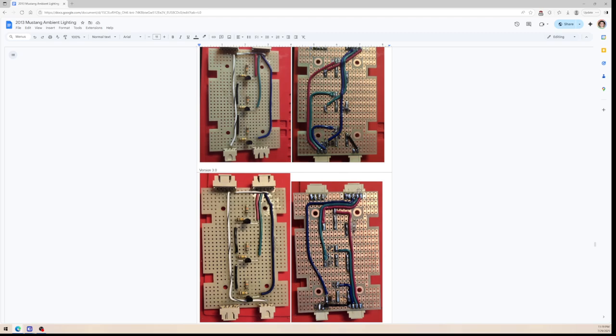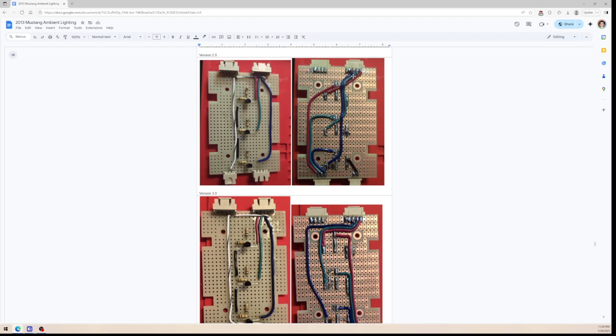Now I do recommend, when you're going to attach your pigtails of your JST connectors onto your LEDs, I would leave this board open so you can see, okay, here is my 4-pin connector. I need to do red, then green, then blue, then my voltage. Okay? Up here, same thing. Red, then blue, then green. Sorry, red, then green, then blue, then voltage.